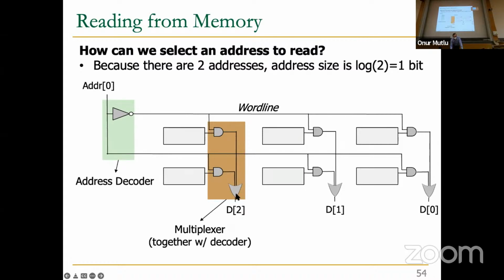Basically, when the address is 0, the output of this data value is dependent on whatever comes out of this bit. Makes sense, right? And that's essentially multiplexing. This structure together with this structure is really multiplexing the value based on the address. Address is your select bit, and the 2 data bits are actually data bits stored here and here.